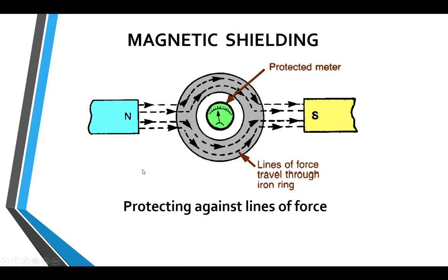Now here's an example where I would like to have some shielding, because here I have a sensitive meter. Maybe this is measuring something very small, like the heartbeat of a flea or something. So it's very sensitive. That means that it operates on a very little signal. Very little voltage will drive this meter. So electromagnetic radiation that's coming from sunspots or radio stations or TVs or wherever, if it gets into this meter,